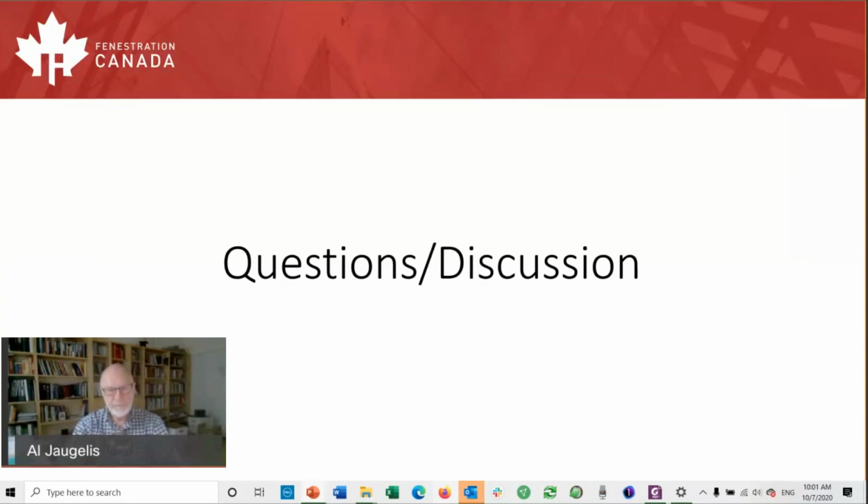Thank you. And then finally, the last question: what does the condensation resistance signify, and how important is that in our climate? The condensation resistance ratings today are not very helpful. If you're comparing two NFRC products and one has a higher condensation resistance number, one has a lower one, you know that the higher one is better. It has more condensation resistance than the lower one. But that's about all you know. You can't predict whether it's going to lead to condensation in your house or not.